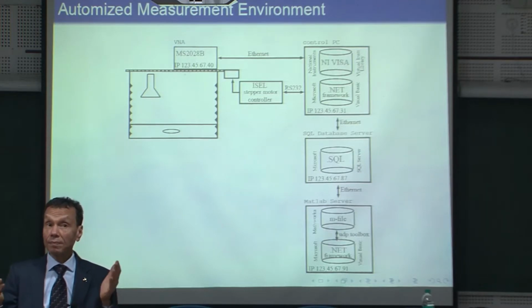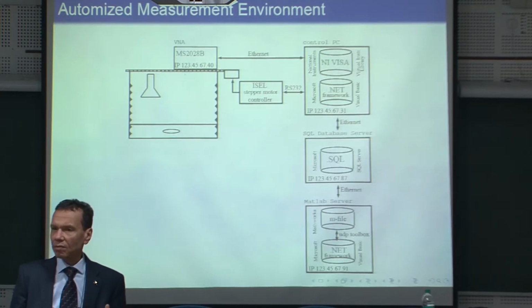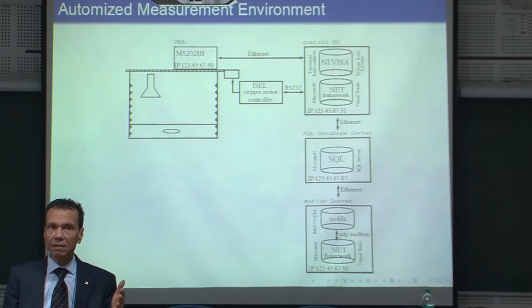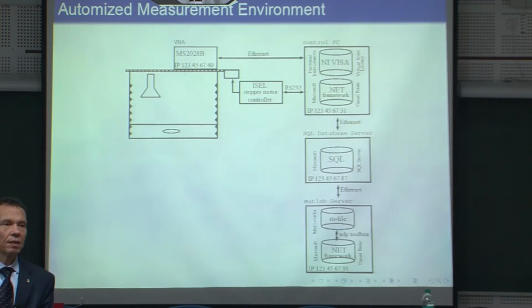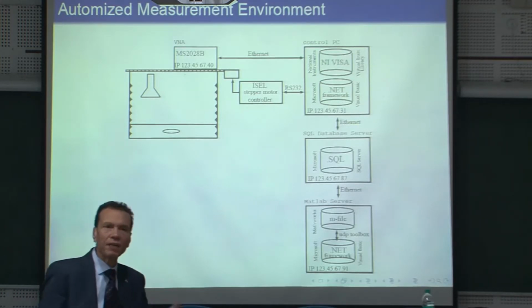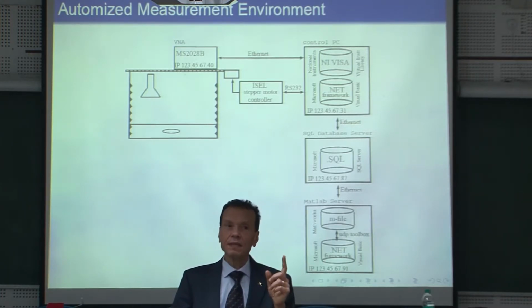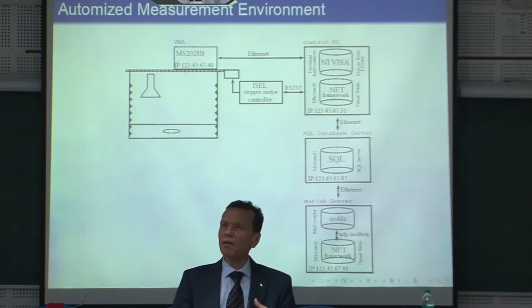Okay, and then if you have a fast digitizer, you can mix down digitally, which is called a digital down converter. Or you may have analog again, so you mix using a mixer until you bring your baseband information to a comfortable frequency range where you can digitize and get the data. So it's just refreshing your information.